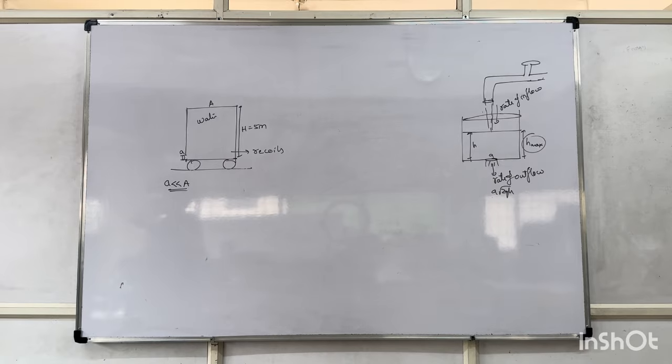Earlier we learned the formula root 2gh for the relative velocity for stage one. Here, root 2gh is with respect to the container, always. My doubt was like this: the outflow exerts a force on the container that causes it to accelerate. Because of that acceleration, won't the relative velocity of the fluid going out change with respect to the container? With respect to the ground, it will change. Height will change, hence relative velocity will change.